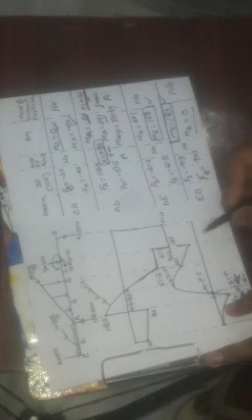Now for the last portion EB, the value of the bending moment at E is 183, right? We have already discussed that there are two values for point E, 168 and 183, due to the external moment added at this point. Previously it was 168. When the external moment of 15 is added, the value becomes 183.